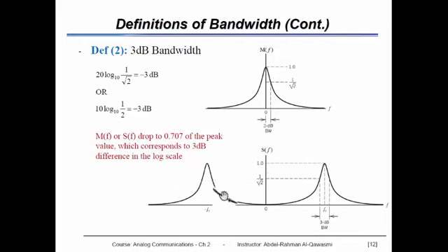On the log scale, this is also 3 dB, but in this, as you see, we are working only with positive frequencies. We didn't consider the 3 dB in the negative frequency, but because this all is in the positive side, so now our 3 dB contains fc from both sides, which means it is the double of this bandwidth. This is because of the process of modulation, the shifting of the original signal in frequency domain as a result of multiplying this signal by higher frequency.